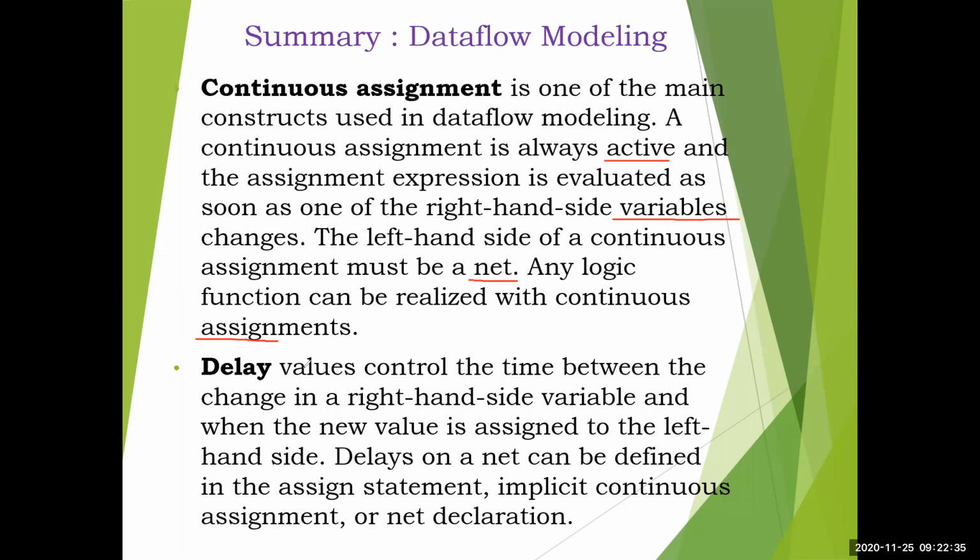Then we saw how to specify delays. Delay values control the time between the change in a right hand side variable and when the new value is assigned to the left hand side. In an expression, the right hand side may compute at time 0, but the assignment will happen after a delay.